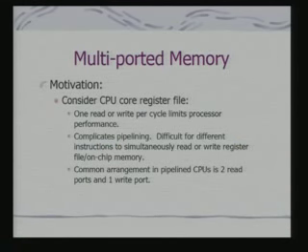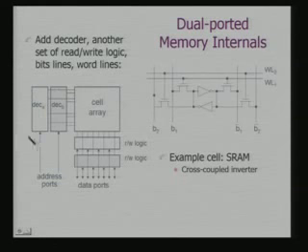So, you can see that we have in some cases dual access memory, single access memory. In dual access memory, 2 read ports and 1 write port is a common arrangement. So, there are simultaneous reads from the memory block. What does that mean effectively? If I am talking about a multi-port or dual port, it means that I have additional decoders.